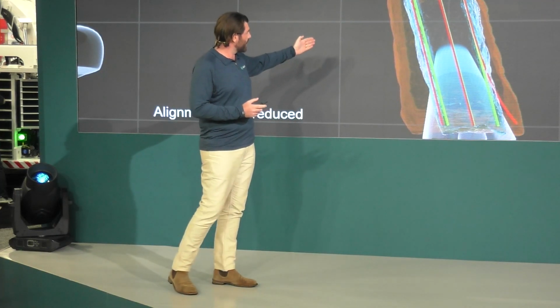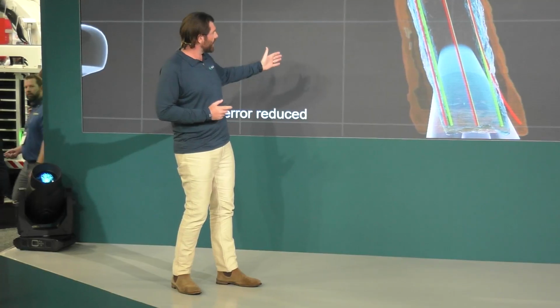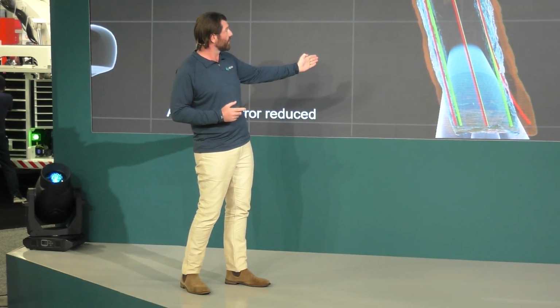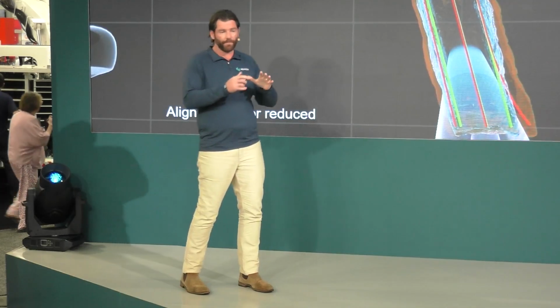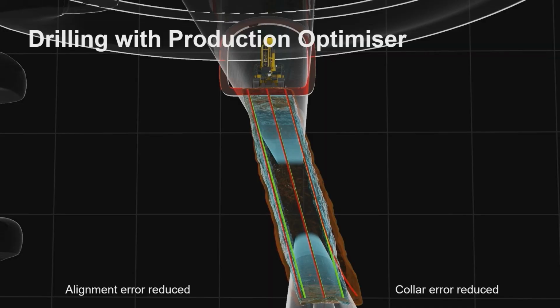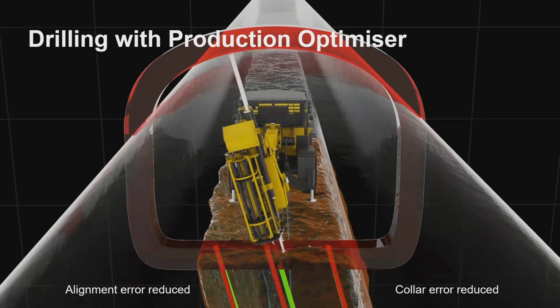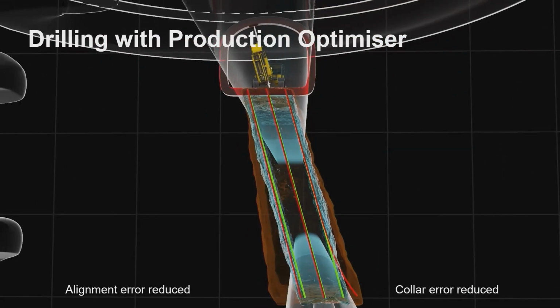And as you can see here on the bottom left, we start to see through the alignment improving, we see the stope performance improving. And in oranges, we've got the actual bulk material. And in this circumstance, we're reducing the overbreak. Now, by reducing the overbreak, we're going to reduce dilution. But what that means for the operation is our load, haul and processing costs are going to reduce.